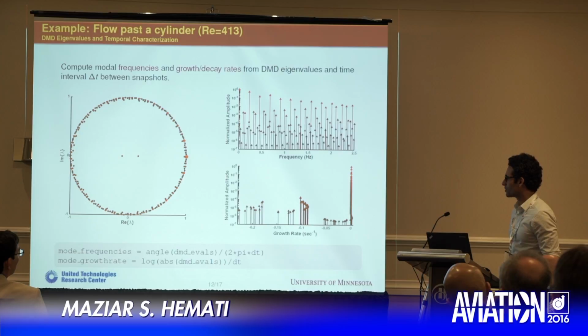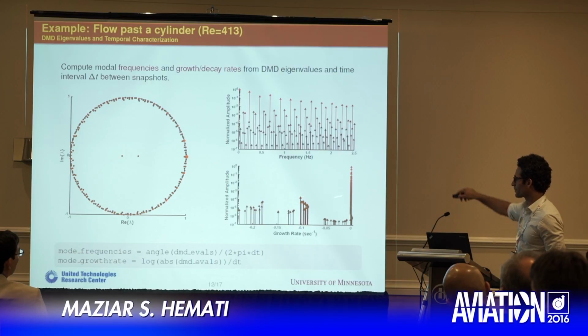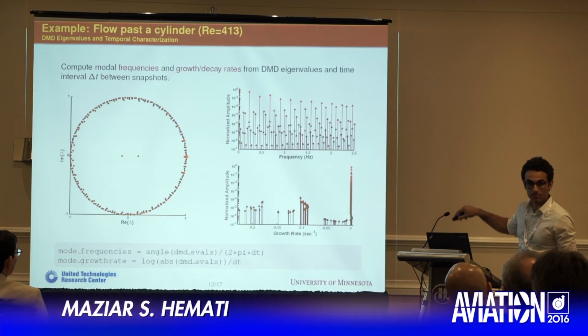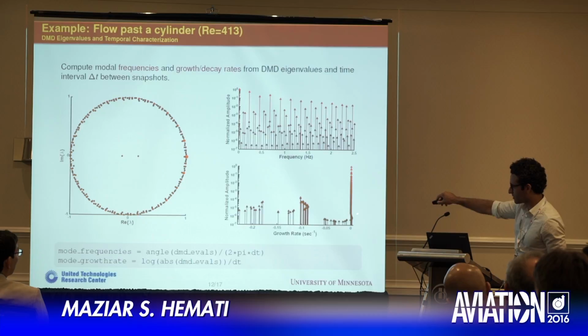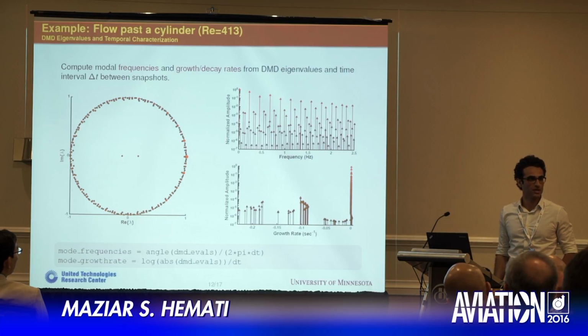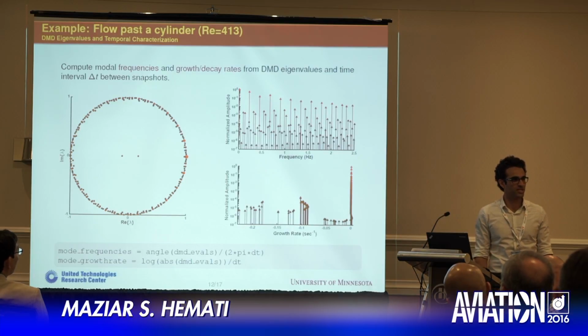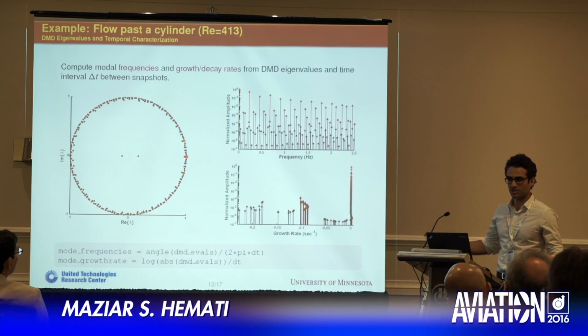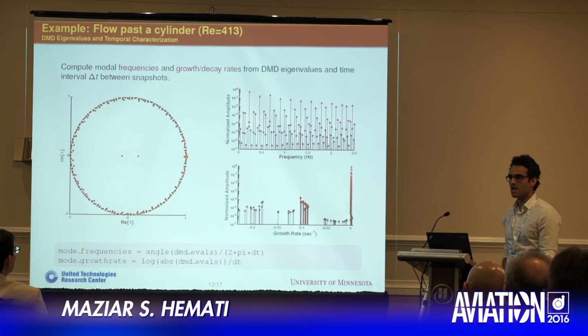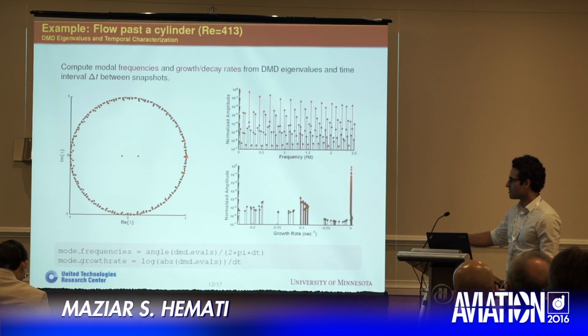It's just a persistent wake flow. But we also see that there's a good series of decaying modes, and in fact there's also some, if you look close enough, if you zoom into this, there are some that look like they're actually growing. Things like this do happen when you apply DMD. This is probably not physical over here. This is probably just a numerical artifact of the simulation to some extent. So this is something you want to be aware of when you try to make interpretations of what you're getting out of DMD. Okay, but this is basically a synopsis of the temporal content.